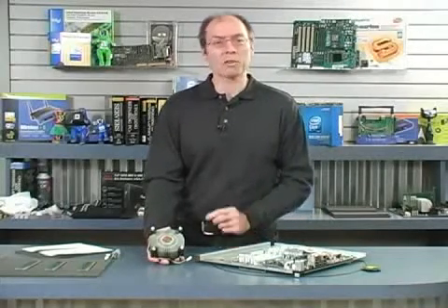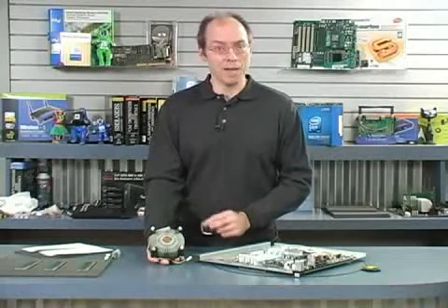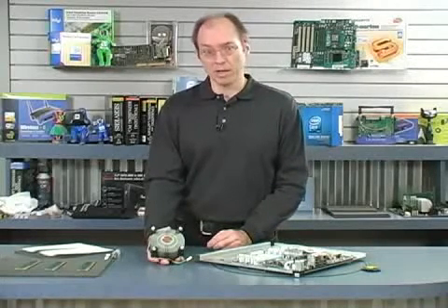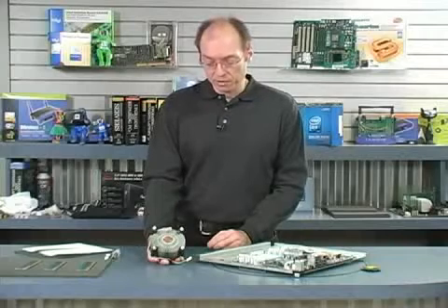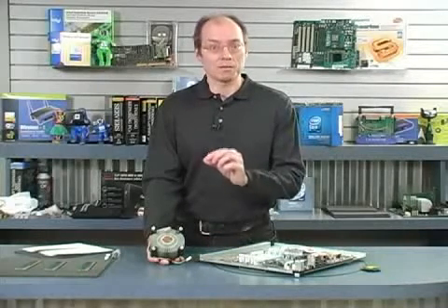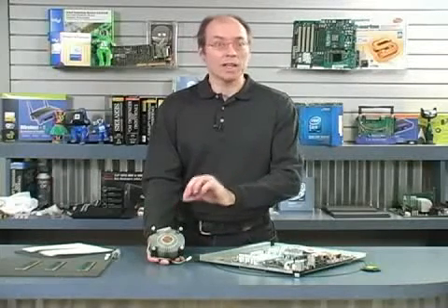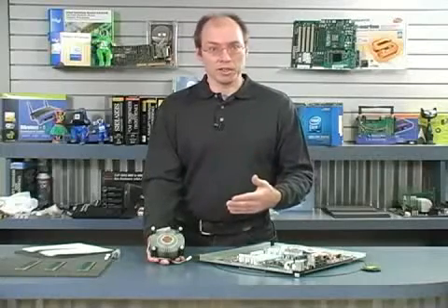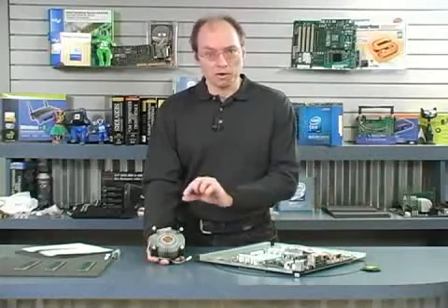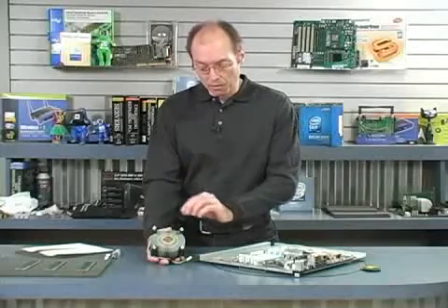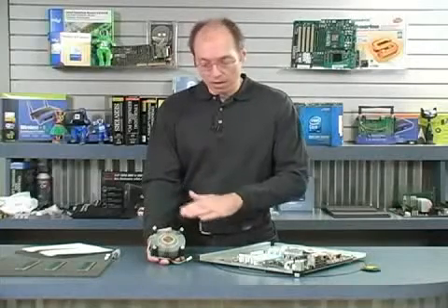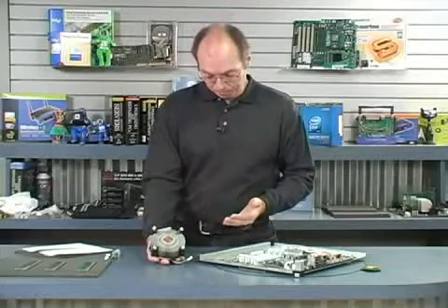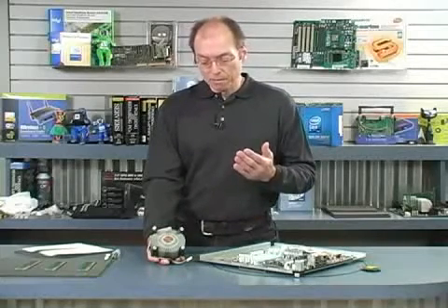Now, thermal interface materials come in two main types. One is called a phase change material. The other is called a grease. Phase change material is a wax type substance that is a solid at room temperature and which then melts at somewhere over 113 degrees. So when the processor warms up, this stuff will melt and then liquefy and perform as it should.